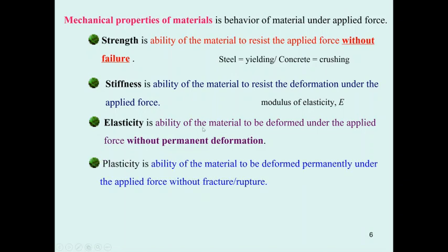For the plasticity, you're thinking about the steel. The curve of steel in the first portion until the yielding has a strain of 0.002. That is the elasticity of the steel. However, after steel goes to the yielding region, goes to the strain hardening region, and goes to the necking region, steel will fail at a strain of up to 0.3, or about 30% of its original length.